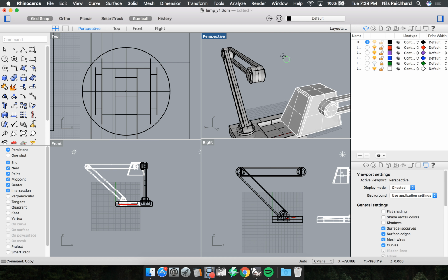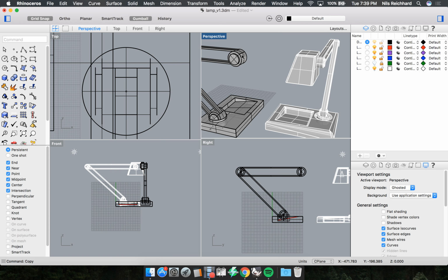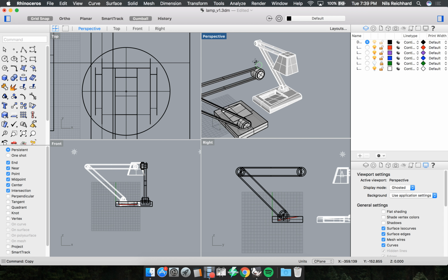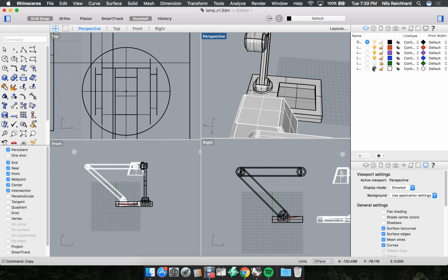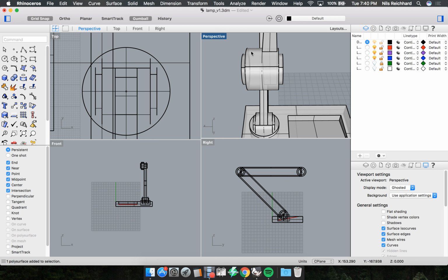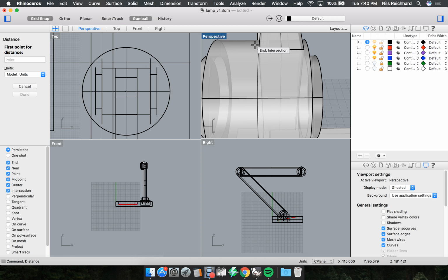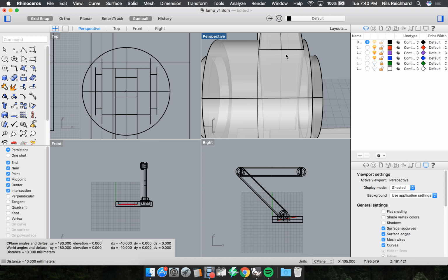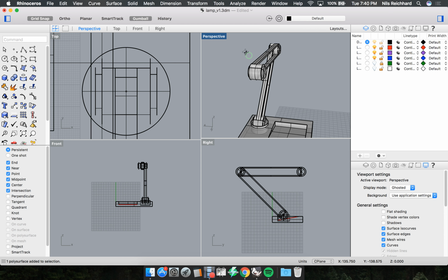So great. Now we have to add this cube and remove what we don't want from here. So the light is looking inwards. I'll move this one. I can move a little distance. You know, we know that the distance from here to here is 10 millimeters. Let's say here to here, 10. So I can move this one by pressing on the red arrow, -10, enter. It's gonna move 10 millimeters that way.